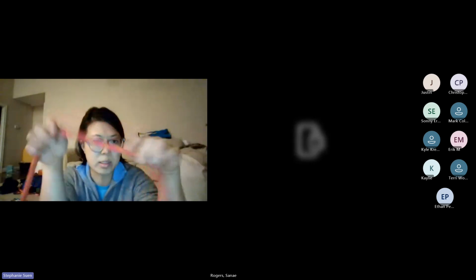Whereas dynamic rope is often used in the rock climbing world, and they're actively taking falls on this style of rope, right? So it's got some stretch to it. You would have to read the manufacturer's spec to get information explaining whether it was static or dynamic, and that this dynamic rope was rated for 7 falls of X number of kilonewtons, right? So do save and read your manufacturer's spec on your rope.